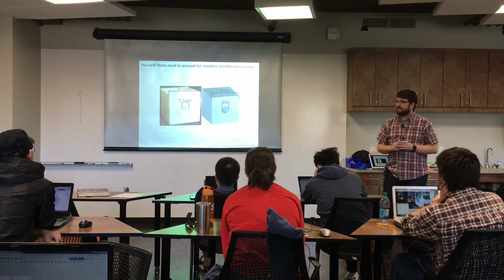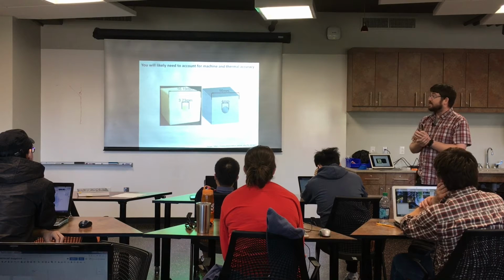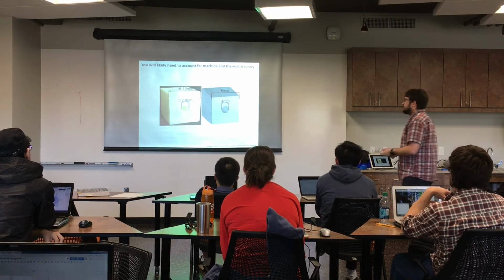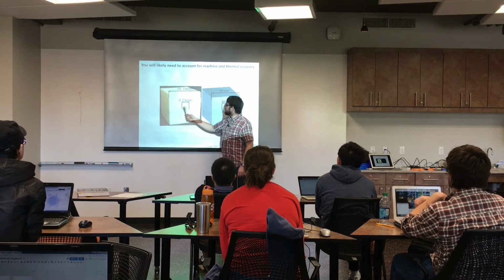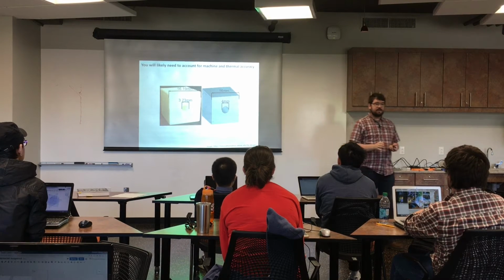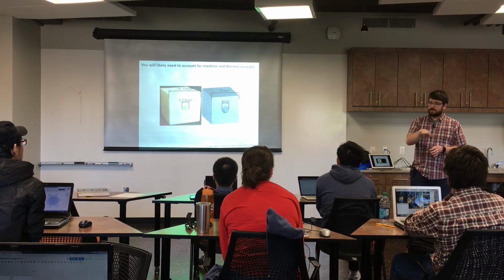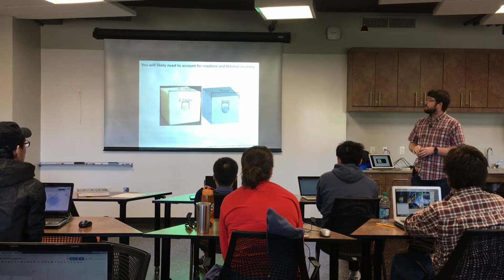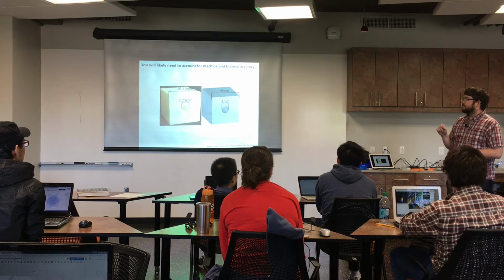The other thing is the accuracy of the machine is not, I'm going to say it's not necessarily constant due to the machine and due to the thermal contraction of the plastic. So if you put in this CAD design, you might get something that's a little bit wider and the hole is a little bit smaller than you wanted. And unfortunately, this varies. The printer has different resolutions in X, Y, and in the Z. So the horizontal axes have the same resolution. The Z axis has a finer resolution. So if you have a vertical hole through a part versus a horizontal hole, it will have a different